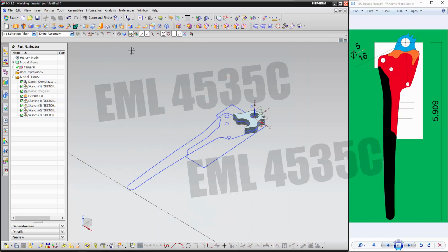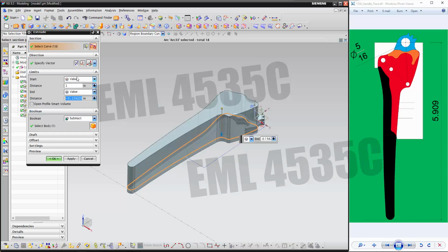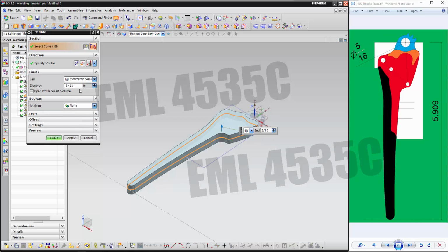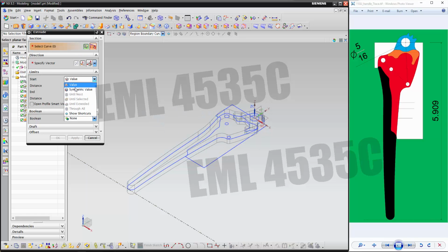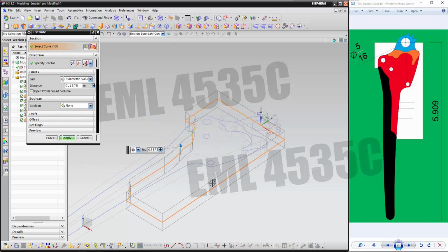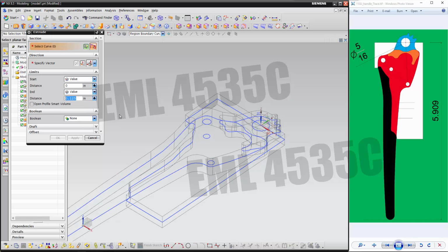Then we'll extrude the multiple sketches. The first is this portion. Okay, this portion will also be symmetric, and 3/16. Again, you can measure from the part we provided. So apply. That's first extrude. Then we'll do another symmetric extrude for this sketch to cut the middle, and that height should be 1/4 in total, so 1/8, and apply.